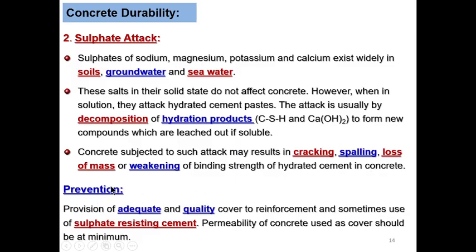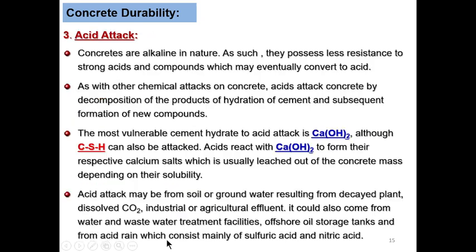What are the preventions? Provision of adequate and quality cover to reinforcement, and sometimes use of sulfate-resisting cement. Permeability of concrete used as cover should be at minimum.